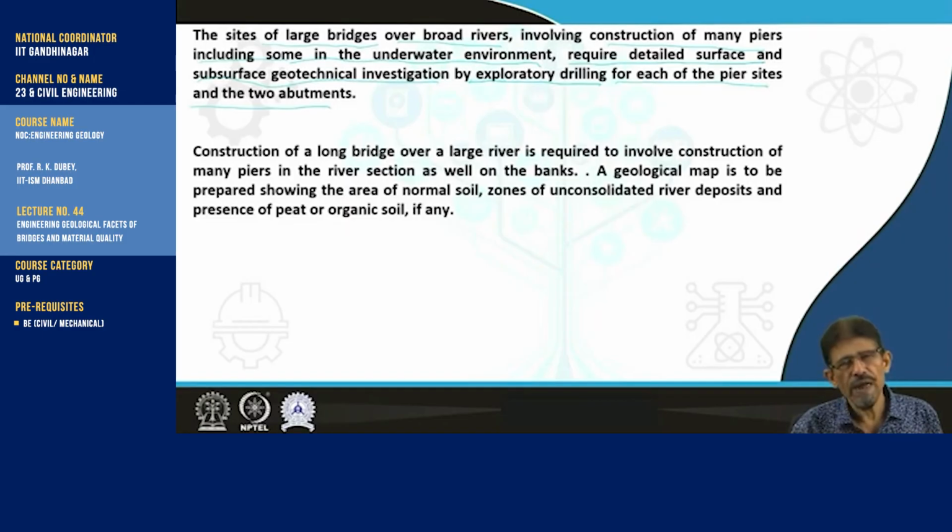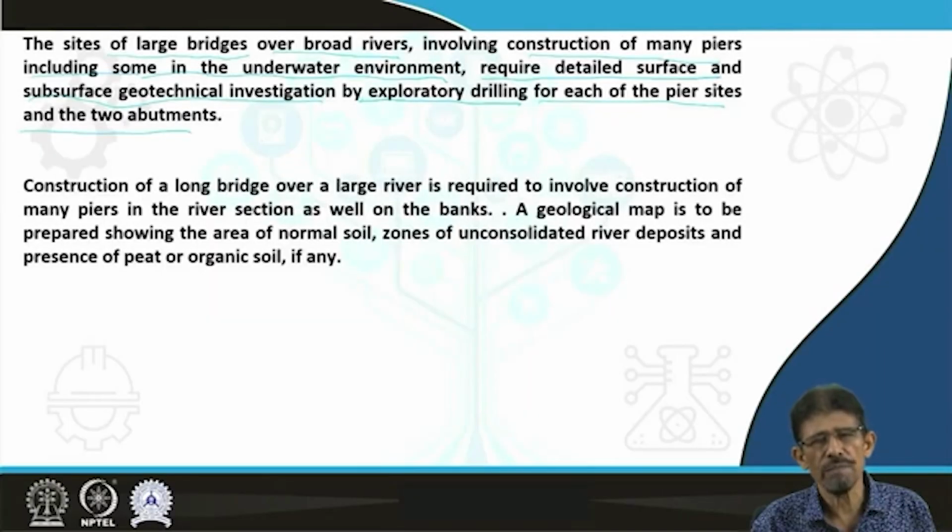So, detailed geological, engineering geological, and geotechnical investigations are required to determine the lithological distribution of subsurface strata or layers, the petrological characteristics of subsurface strata, as well as the bearing capacity, cohesive strength, shear strength, compressive strength, and tensile strength of rocks, as well as soily or loose material.